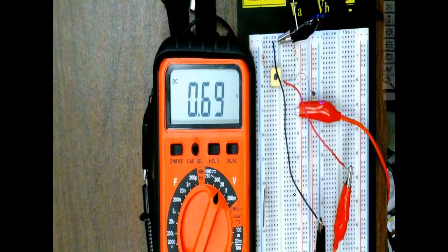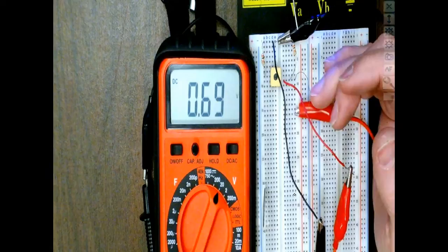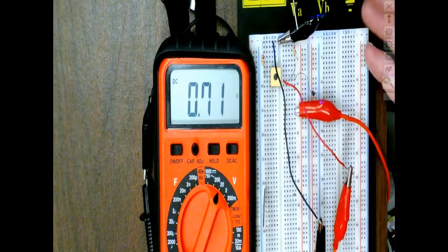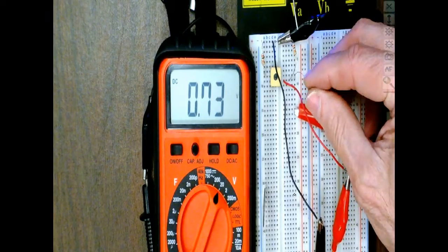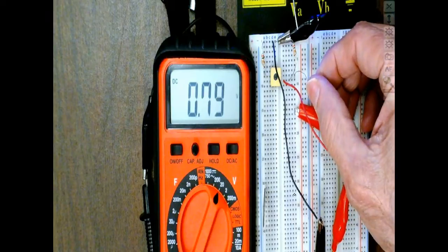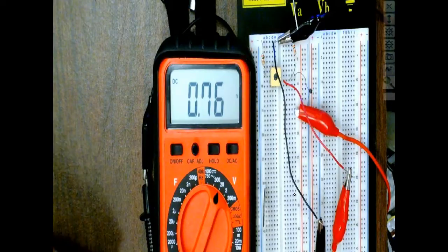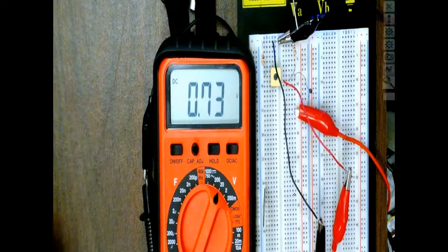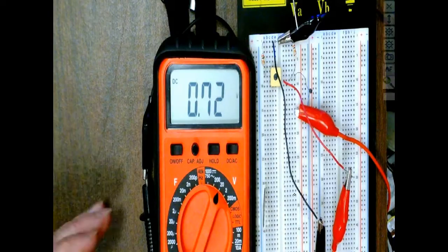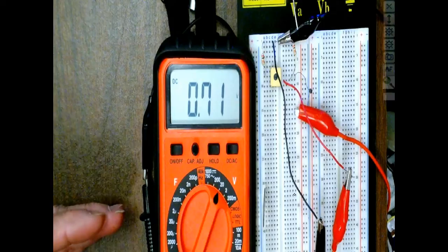So what's nice about the centigrade scale is that 0 is freezing. So what that means is, if I could take this thermistor and put it into something that's freezing, and normally what they would do is put this into a cup of ice water, stirred up real good, and immerse the thermistor down into the ice water, and then we would have a voltage that was relative to 0 or freezing.